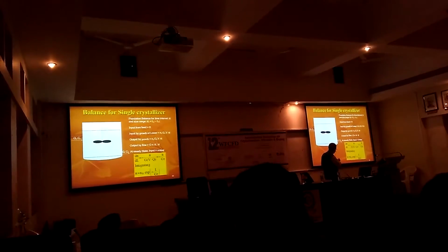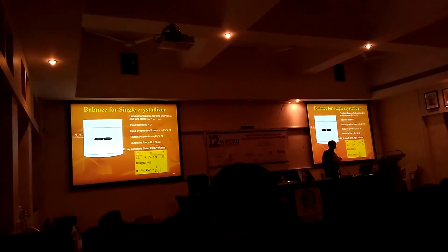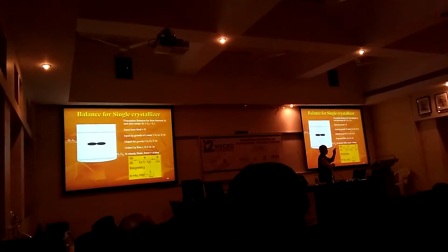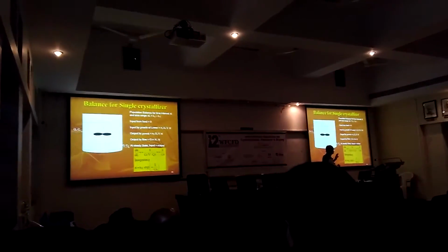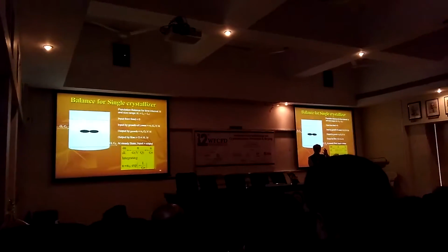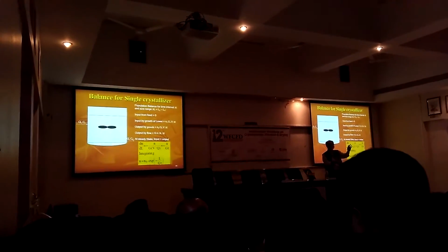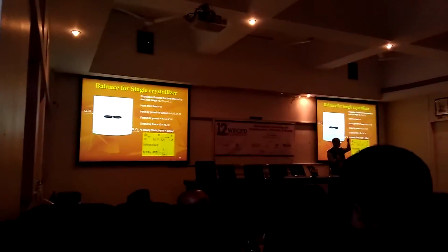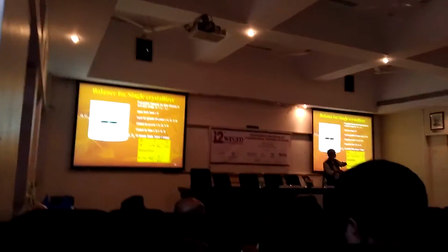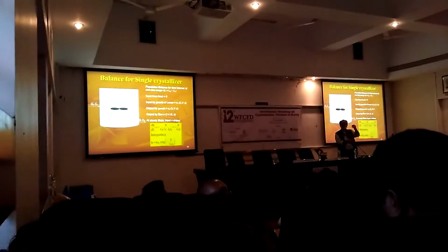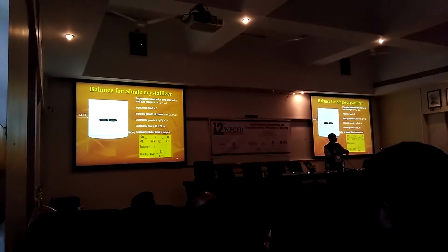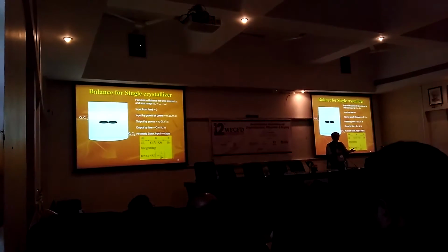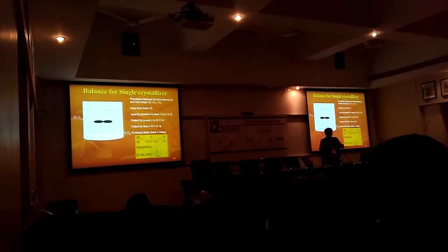The population balance, as indicated out here, is: you use a specific size interval, and you say that in this delta L size interval, I have N1 number of crystals. So if I take a summation of this or integrate it over the entire size range, I have essentially accounted for every particle which is present in it, and every particle, when accumulated and added in terms of its weight or mass, would give me the total weight of the solute which I am planning to precipitate out.